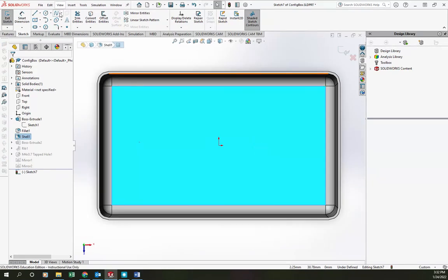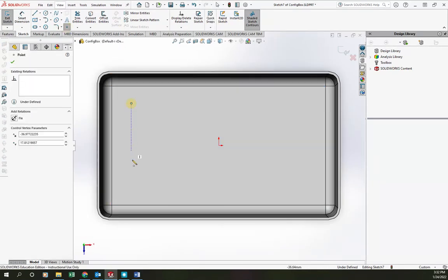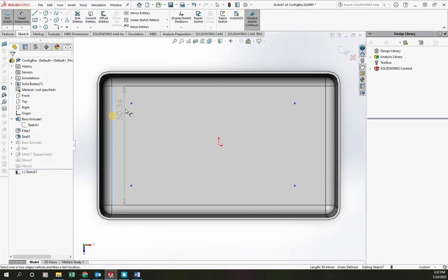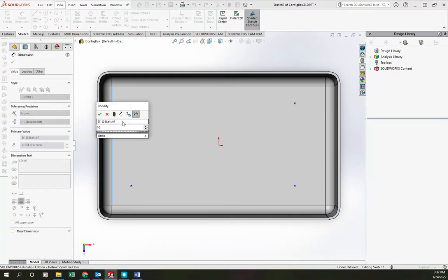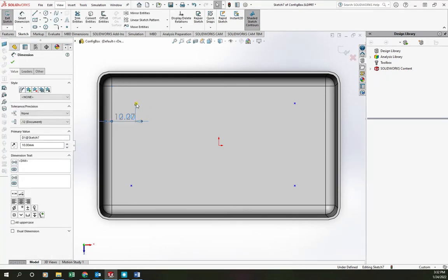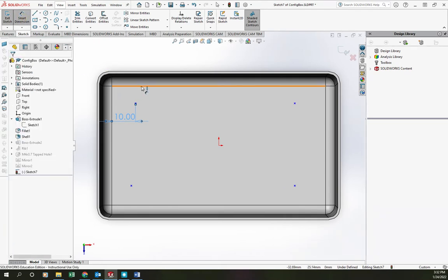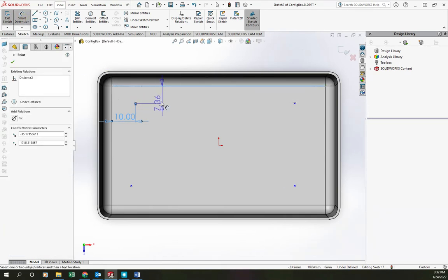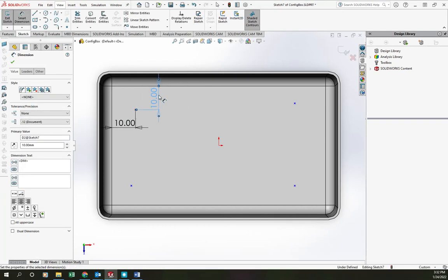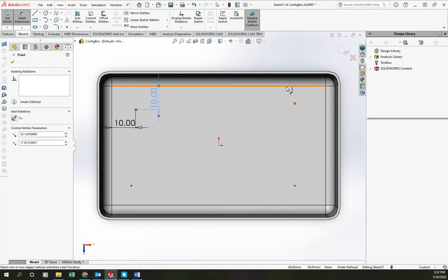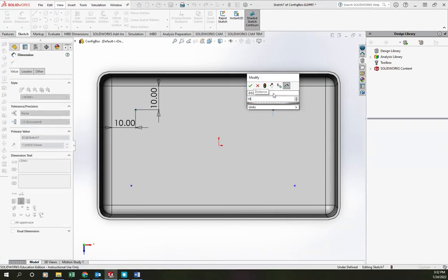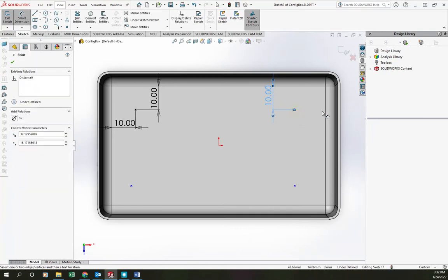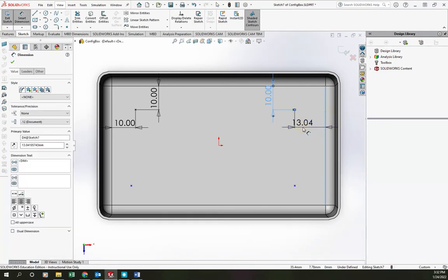And we'll use the same positions for each of these as we used for the center of our holes in the previous example. So I'm going to put the centers of all of these at 10 millimeters from the sides in each of the directions. Now if we want to use different positions for these, we could, but we do want to make sure that if we change the size of the box, it doesn't get too close together or too close to the sidewalls or anything like that. So this is kind of a conservative value.